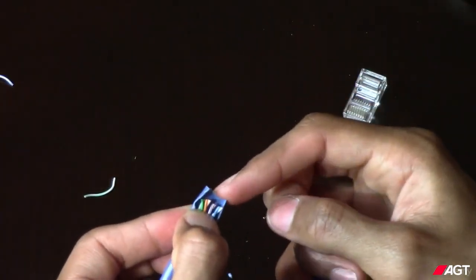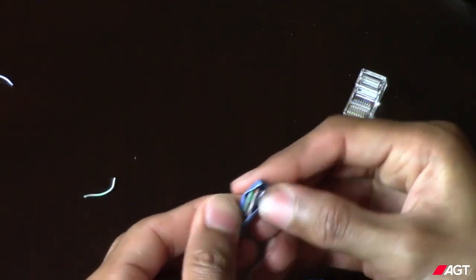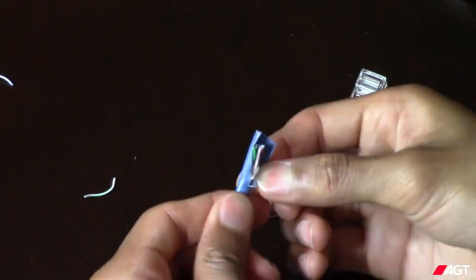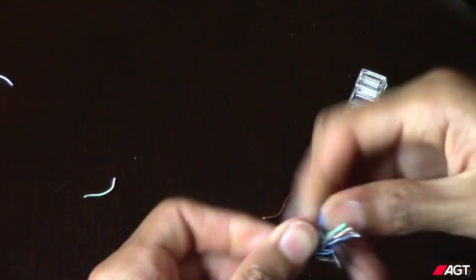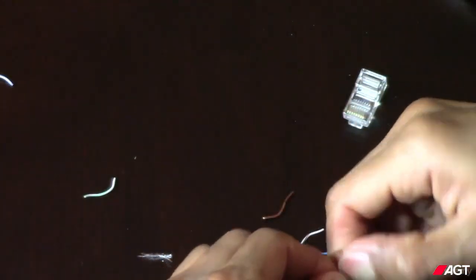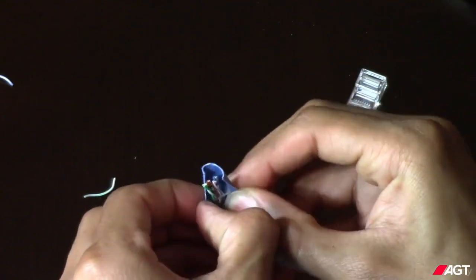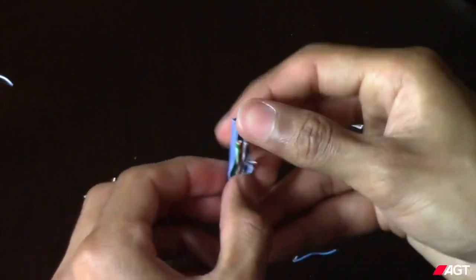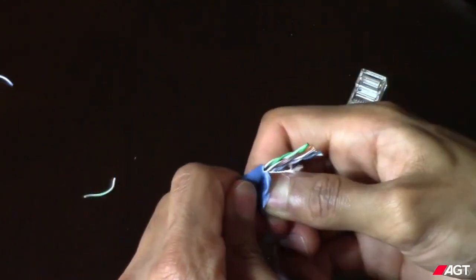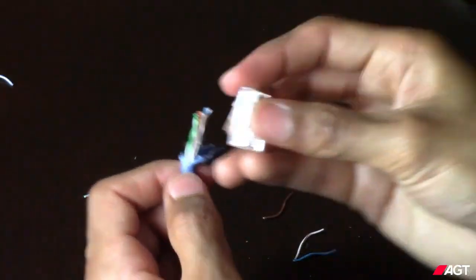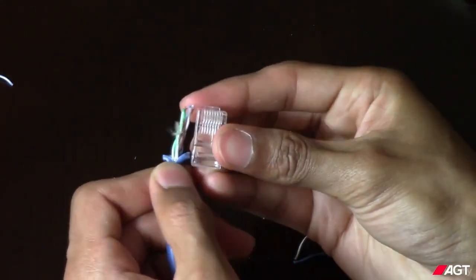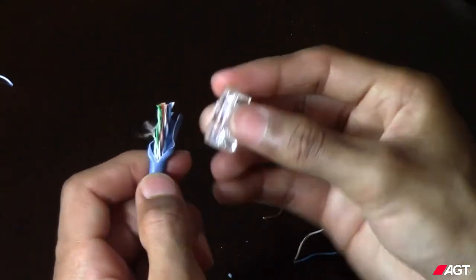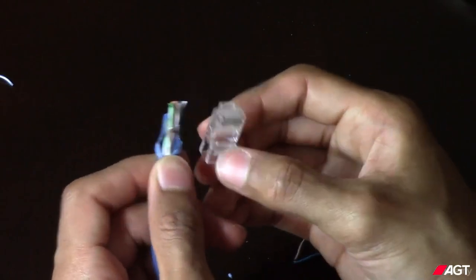At this point, you want to make sure that your shield is longer than your wire, just to be extra certain that there's no damaged wire left in the cable. Slowly open up the sheath a little more using your hands. Now you can use the connector to measure where the sheath should end. You're eventually going to want to cut off a few millimeters of wiring to make sure that they're even at the top. And we'll be using a crimper to do that in just a minute.